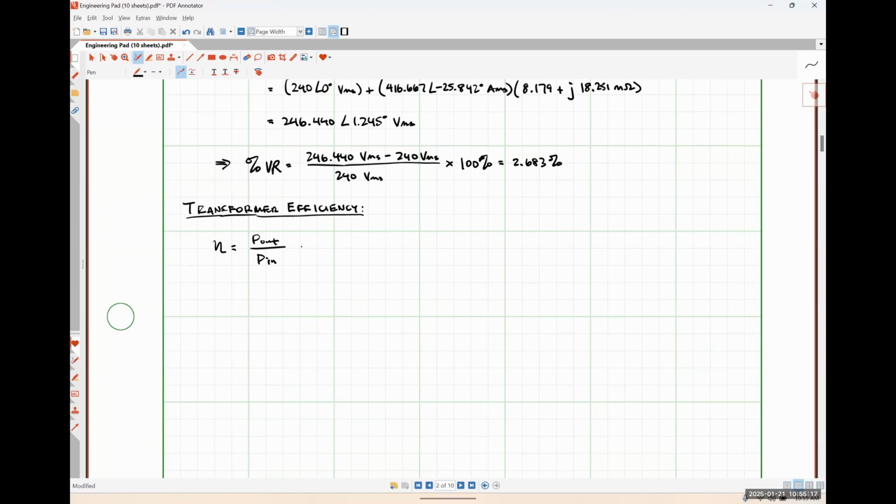So we can express the input power in another way, so let me put P out up here again. The input power is nothing more than the output power plus any losses that we have. That's the difference between those two quantities. So I could write P in as P out plus P losses. In this case, I'm going to take into account specific losses for our transformer. So we are going to have our core losses, and then what are called our copper losses.